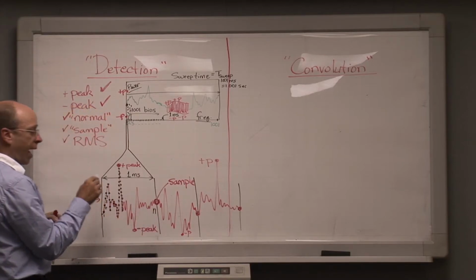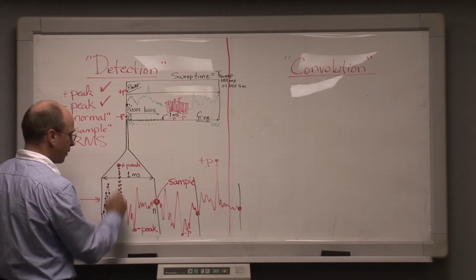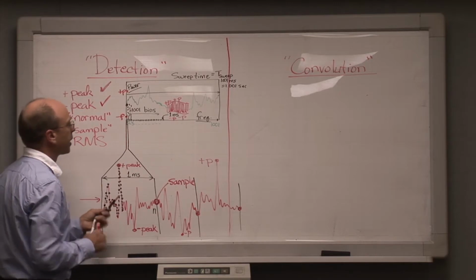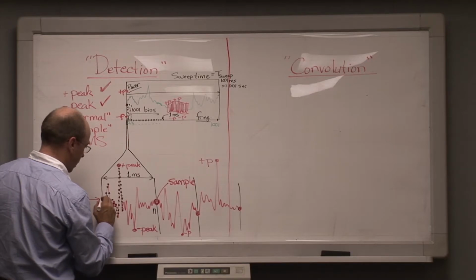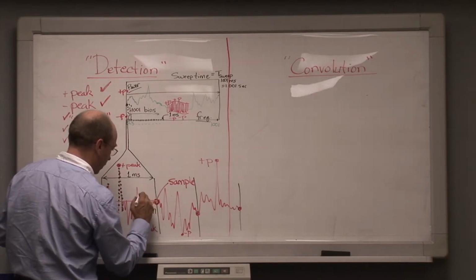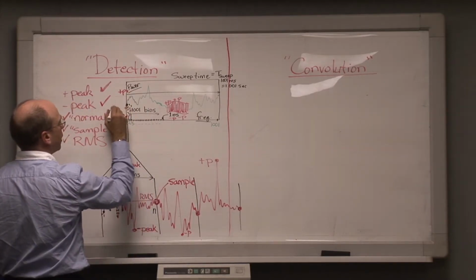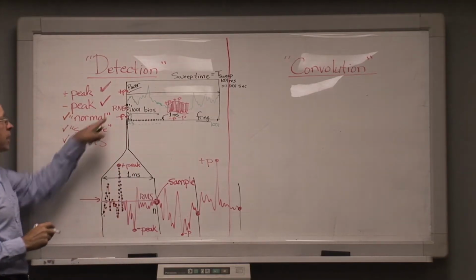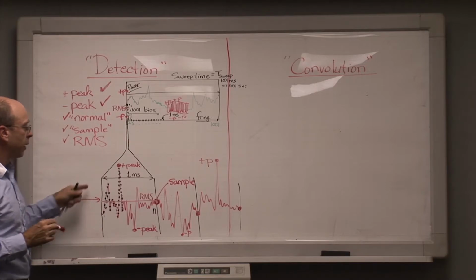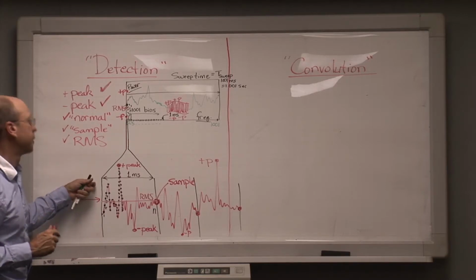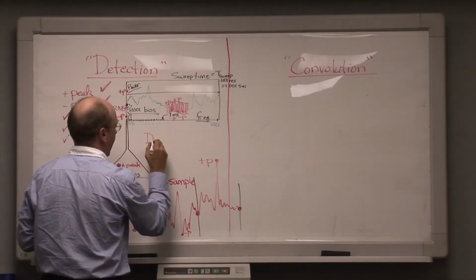And then we take the actual linear power average, not the decibel power average, but the linear power average of all of these values in this bin, and that will be displayed as the true root mean square power value, which for this bin, the way that I've drawn it, might be a level that might look something like that. And so root mean square would presumably be a power value like that for the first bin on this spectrum analyzer display. Now, there are a couple of other averaging techniques available on analog and digital spectrum analyzers. One of them is a so-called decibel average.